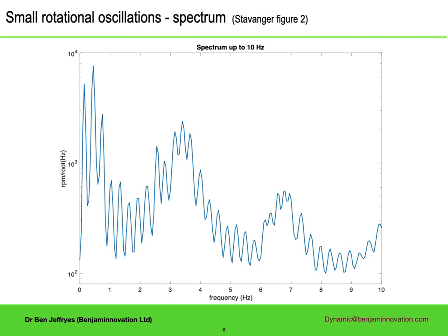Remember, this data is measured in the BHA, and there is a large impedance contrast at the top of the heavyweight. So if a multiple of half a wavelength of the vibration is close to this length, there is an enhanced resonance.